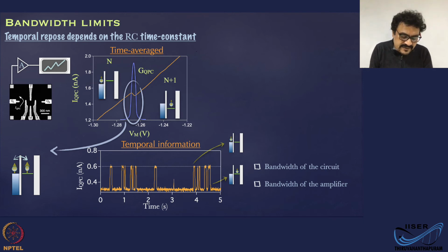So generally what you have is a quantum dot device, and when you are measuring the current through the sensor, that is a channel, you will get a bump-like structure, or peaks in the conductance, as a function of one of the gate voltages. That's going to tell you when the charge transfer is going to happen.